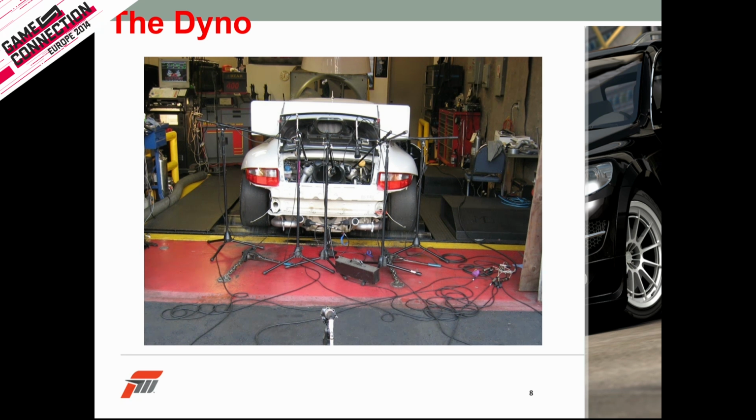There's another type of dyno called a Dynapack, which is actually preferable for recordings, where it's a resistive system that bolts directly to the wheel hubs of the car. You take the tires off of the car and you bolt these resistive boxes onto it, which works really well. And then you can also take a car just out on the road, out on the track, and figure out ways to put microphones up on it.